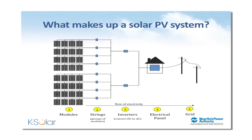Then those are all combined together in the wiring, they all go to a central unit called an inverter. An inverter basically converts the DC energy coming from the solar panels to AC energy that your school can then consume. That is then connected to the electrical panel of your school. So your school has a dual feed now. Has one feed from your electric utility, another feed from the solar panels that are going to be on your roof. So the two systems are running in parallel, your electric utility and your solar system.